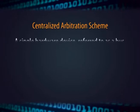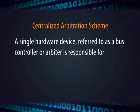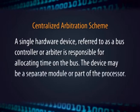In the case of the bus arbitration method, more than one module may need control of the bus. Since only one module at a time can successfully transmit over the bus, some method of arbitration is needed. The various methods can be classified into two groups, centralized and distributed. In a centralized scheme, a single hardware device referred to as a bus controller or arbiter is responsible for allocating time on the bus.